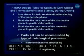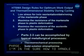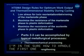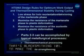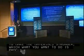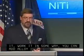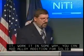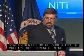And I'm not really sure how to handle the first one metallurgically, but the second two processes, that's basically blacksmithing 101. To make the material stronger, what you want to do is just either thermomechanically process the material, cold work it in some way. You could add alloying additions for solid solution strengthening, or you can do something to induce precipitate strengthening. So that's what we've done with some of the high temperature alloys. If you go to the next slide.